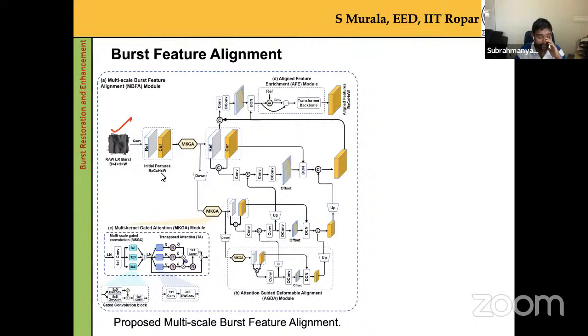So that's why, even if you see the iPhone, it will ask which image you want to consider as a reference frame. Generally, the iPhone collects 9 photographs in a single burst. The center one is considered the reference, and then 4 on the right side and 4 on the left side, total 9 frames in a small burst. So the center one is considered the reference frame.